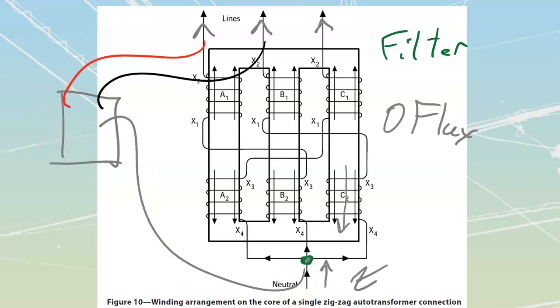And then from that panel, I would be able to distribute out to the individual loads that I have inside there. I take current in from one of these lines over here. It's going to go through my single phase loads, come back onto the neutral, and then it is going to get split up and sent back onto my lines evenly, which is going to prevent me from overloading just a single phase at a time.